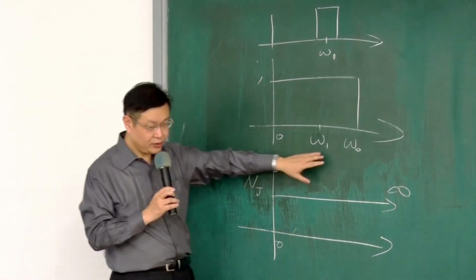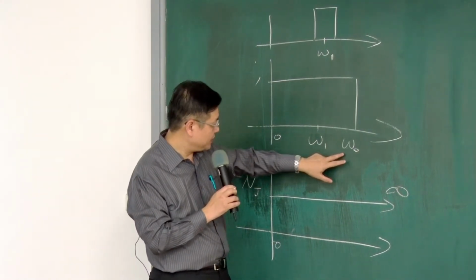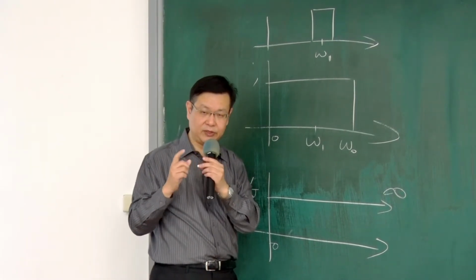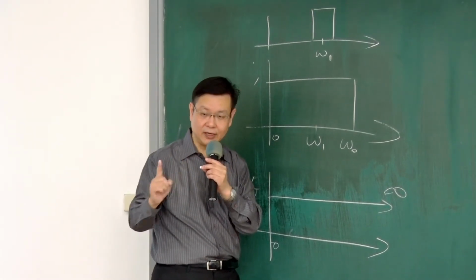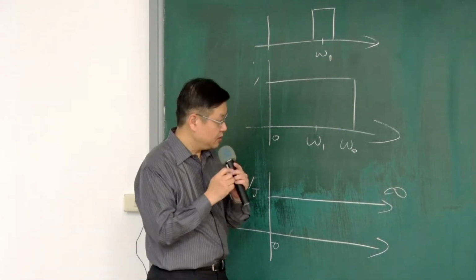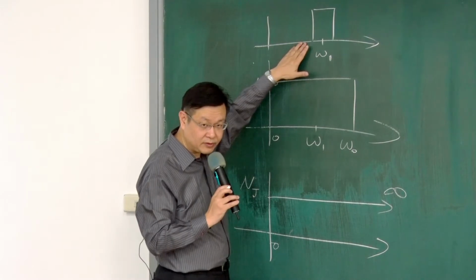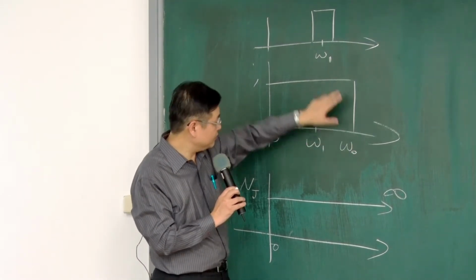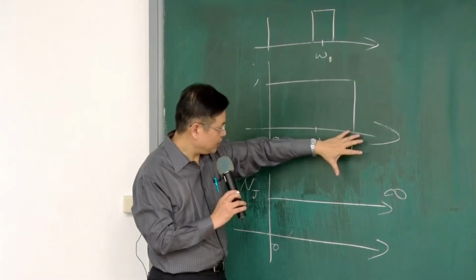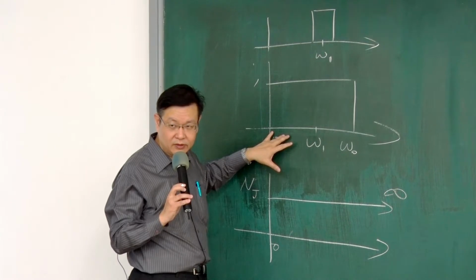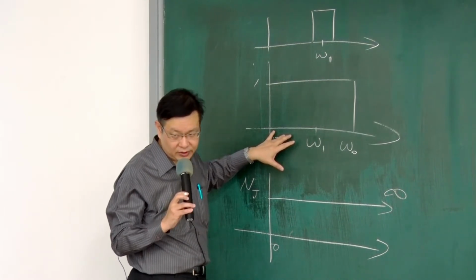For a gyro, usually they are operated at a natural frequency. Actually, the operation mode is they are vibrating all the time at a natural frequency. If you don't do any filtering, the gyroscope will be operated here, and if you don't have a filter, you need to open up the whole window for operating a gyroscope. So the gyroscope will become very, very noisy.